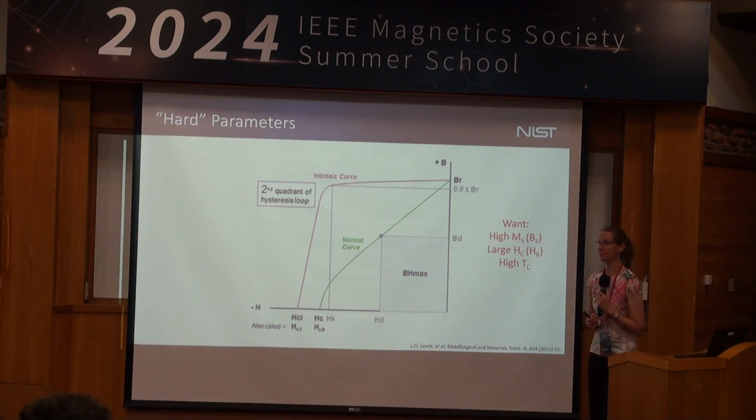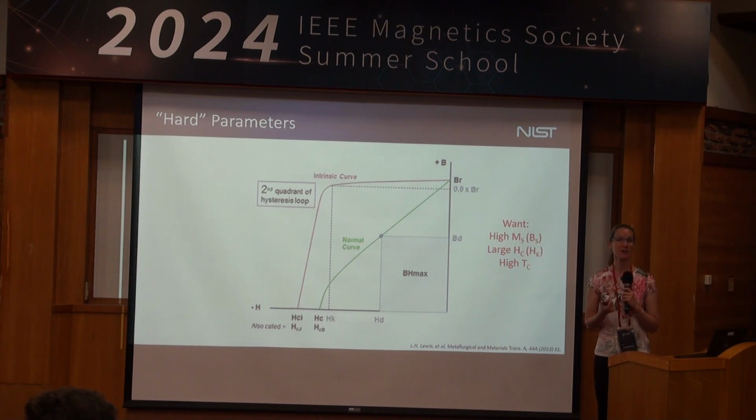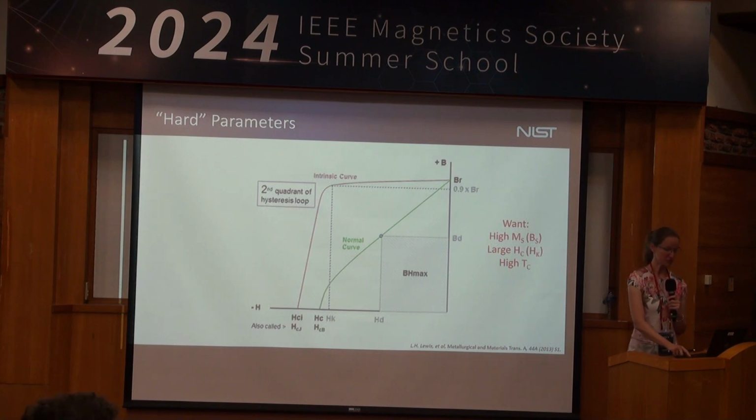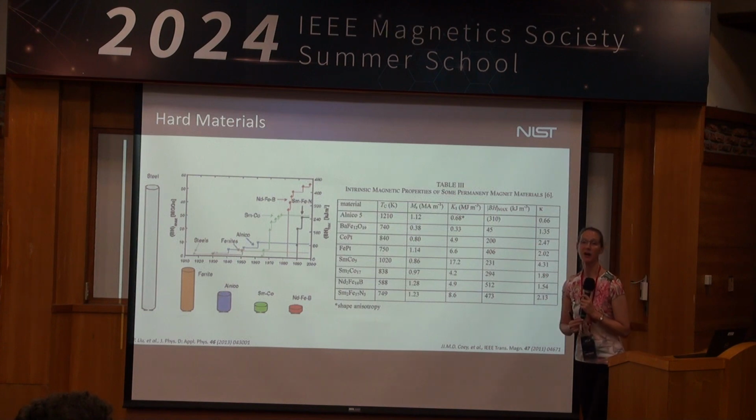But there's a trade-off, and this trade-off is pretty prevalent when you look at different materials because, for example, the hexaferrites are hexagonal, so they have a lower symmetry, but they have a very low saturation magnetization. So it's easy to get very high anisotropy, but you get low MS along with it. You can get a high MS, but then you get a low anisotropy. So you've got a competition here. And so a lot of the work in hard magnets has been all about how do you overcome this contradiction.